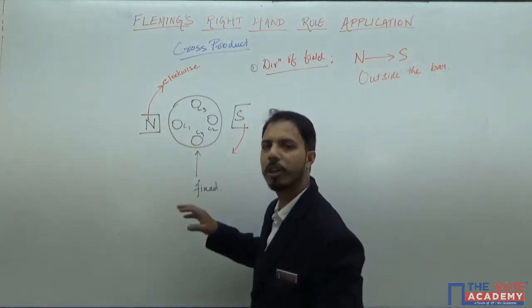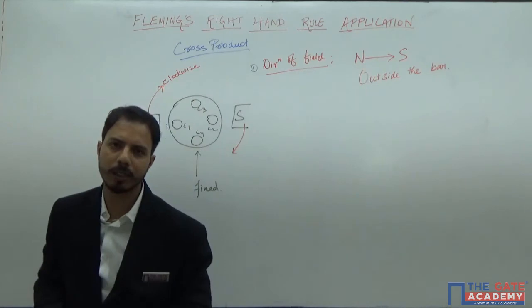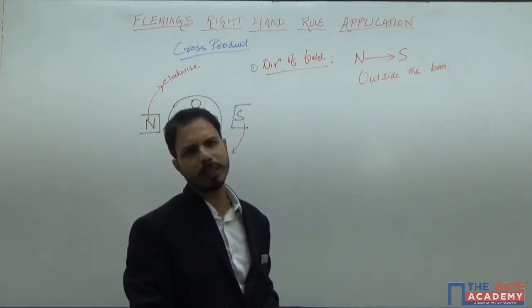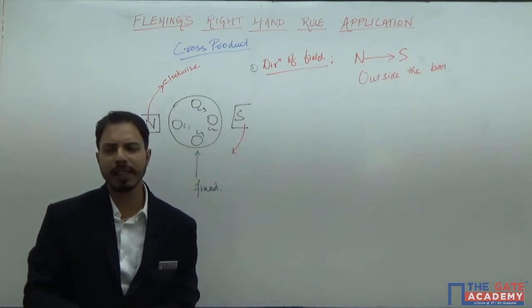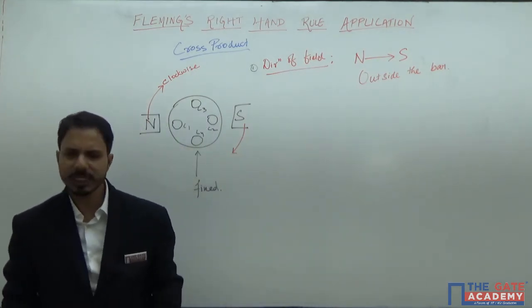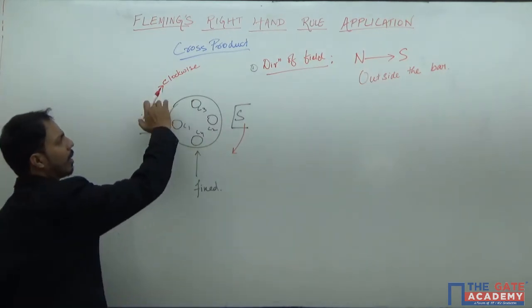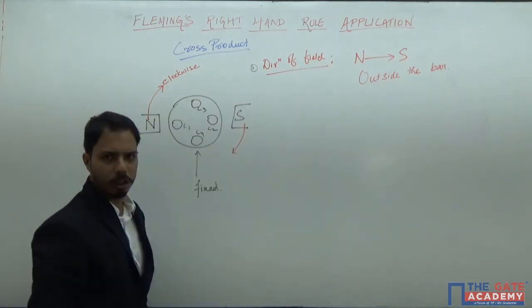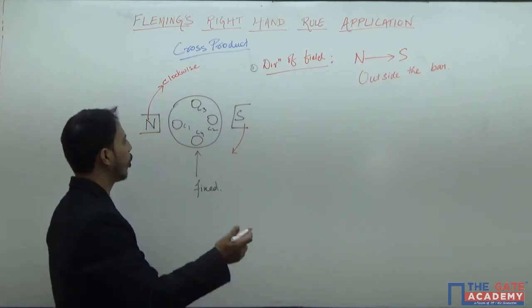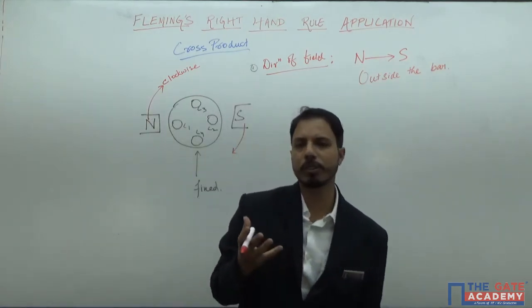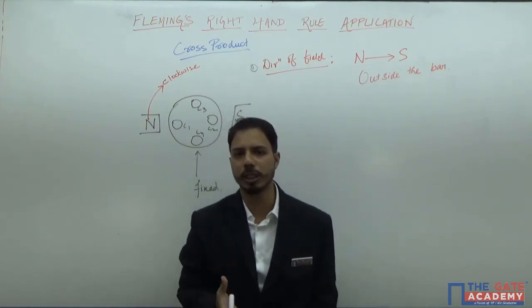In stator we have rotating magnetic field, and the rotating magnetic field rotates either clockwise or anti-clockwise depending on the connection. Okay, so let us say that the rotating magnetic field is in the direction of clockwise. So first of all, in the conductors of the induction motor, there will be induced EMF.